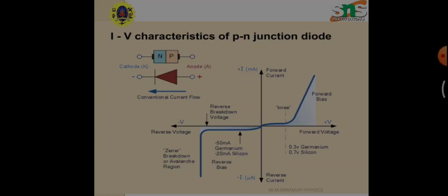The circuit used is shown in the figure. The milliammeter mA measures the current. The voltmeter V measures the potential difference across the diode. The forward voltage is gradually increased in steps and the corresponding milliammeter readings are noted. A graph is then plotted between the voltage and current.